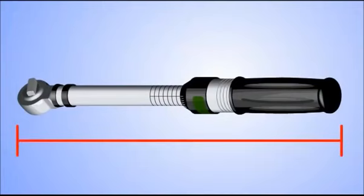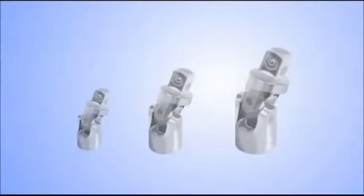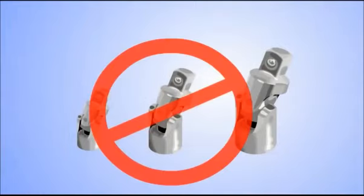Any extension that increases the overall length of the tool, such as a crow's foot, will affect the applied torque and should not be used unless directed by the service information. Also, while they may come in handy to reach tight places, U-joint attachments should never be used with a torque wrench. They'll affect the applied torque and cause you to improperly torque the fastener.